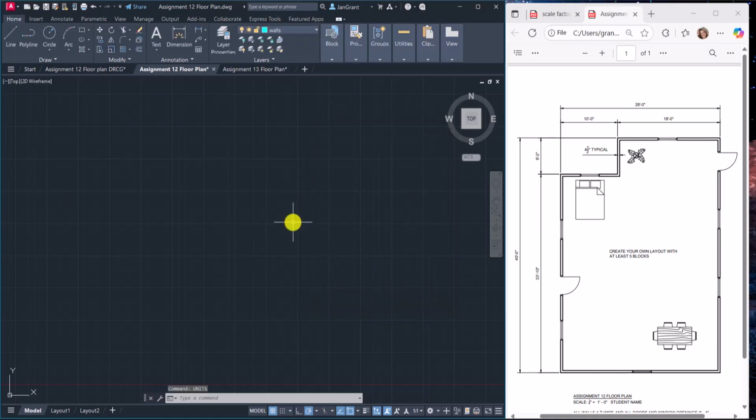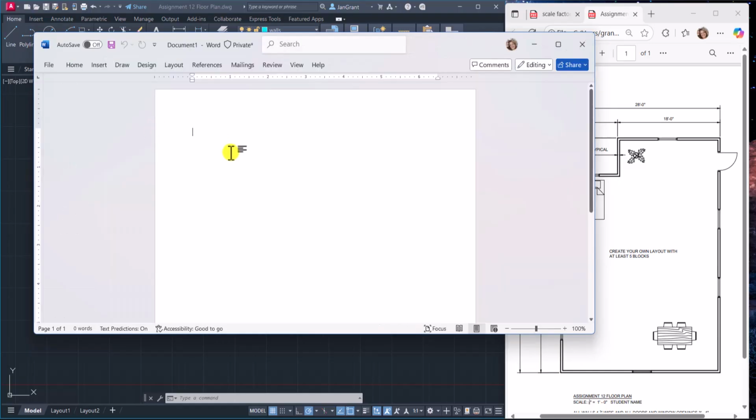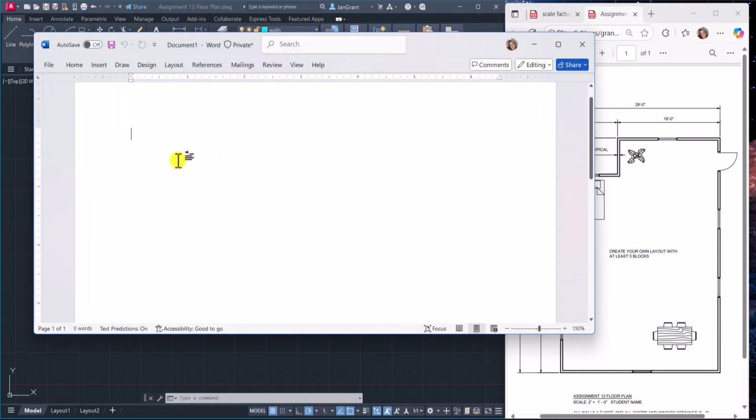What that does is it changes the way you see the numbers on the command line and in the dialog boxes, and also how you input the numbers. So instead of typing in 33 dash, all of this for 33 foot 10, you're going to type in 33 apostrophe 10. So I'll put something together like this. Let me just show it to you.